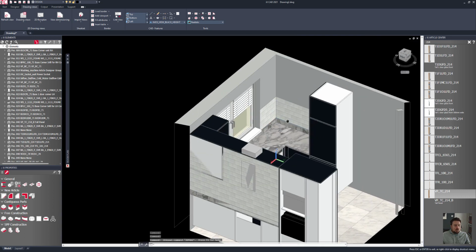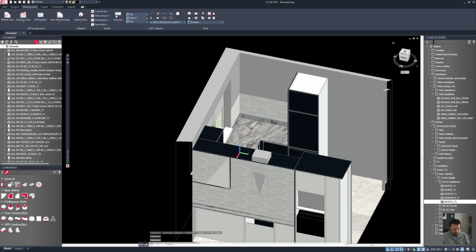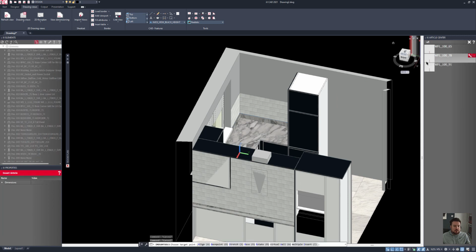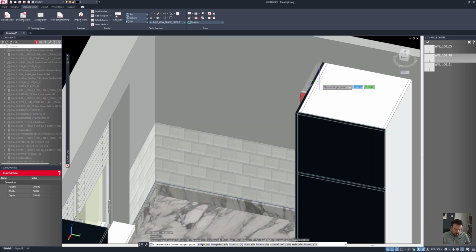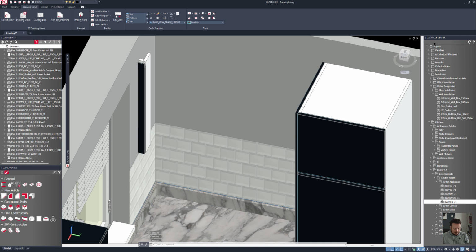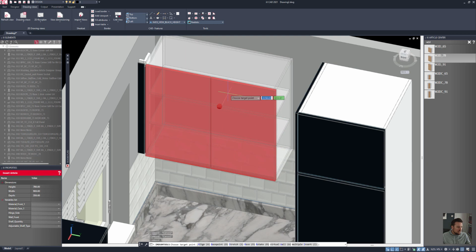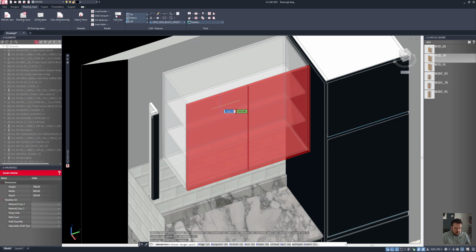Yeah, that's looking good. We need a wall unit in there as well, maybe a double door. So let's go for a wall 2-door. Well, actually, let's put in a wall filler left first, and we'll keep that as small as possible. Let's say something like a width of 50 millimeters, just as an infill in here. So yeah, let's move that with the M key over to one side, drop that down. We then want a wall 2-door, and again I'm just going to drop this into position, and I can then move this around and have that